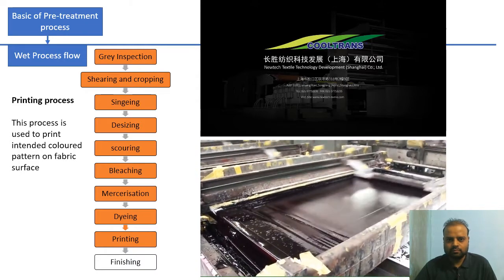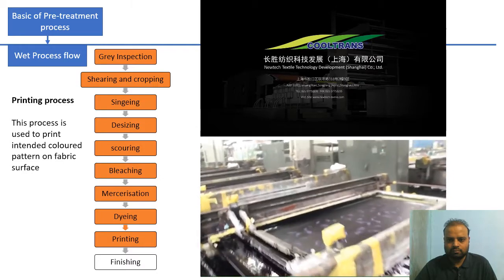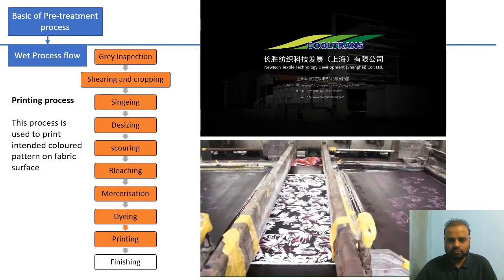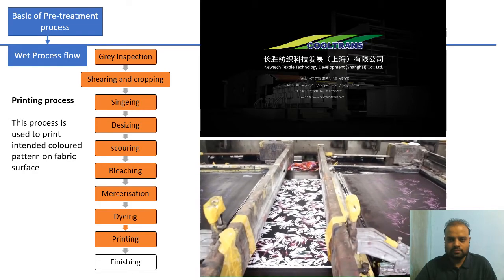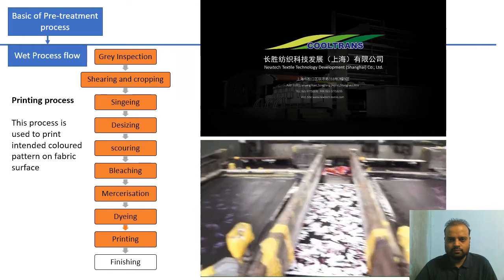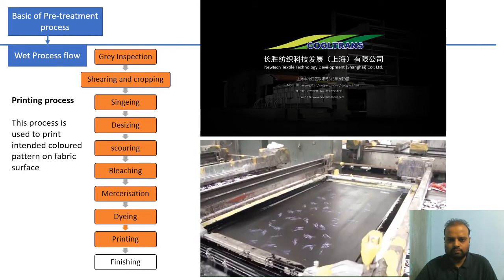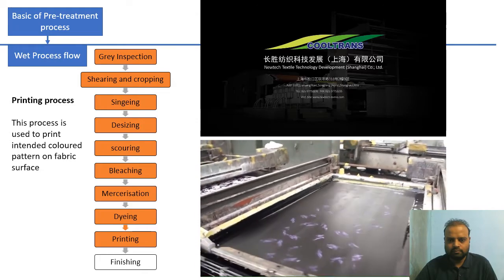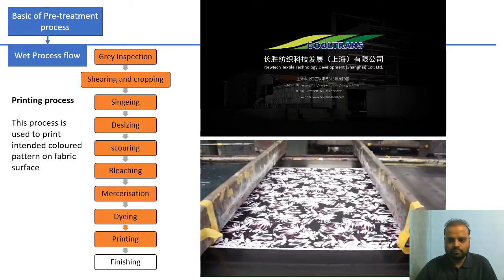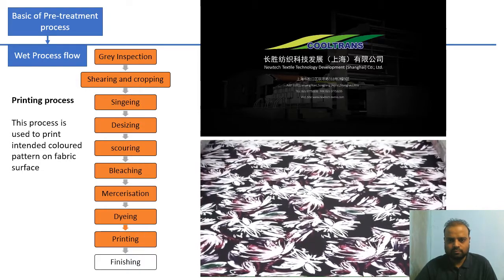The next screen is a pink color. You can see at this stage there are now 3 colors on the fabric: black, green, and pink. Next comes purple. You can see the areas on the screen that are purple as opposed to black. Those purple areas are open. The rest of the screen is closed. Dye is only pushed through those open holes, and this is what allows the dye to be applied to the fabric.